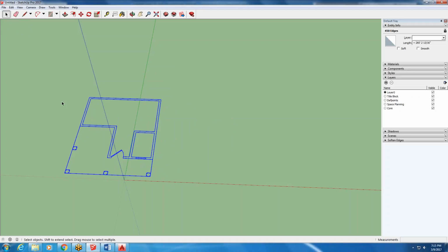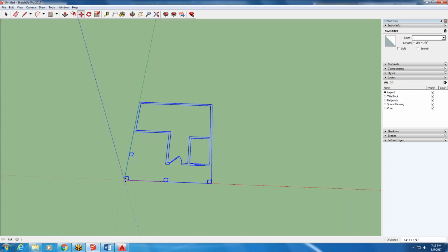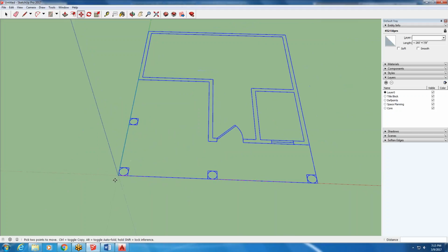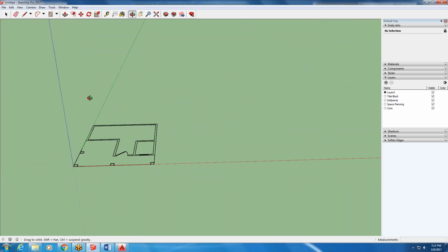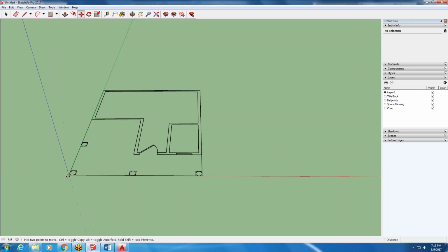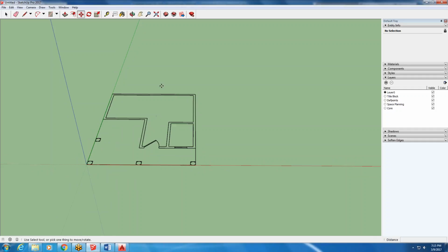Then I'm going to click. I always like click this arrow to get out of stuff when I'm not sure about it. Then I'm going to select it again and move it about this point to this origin point. It's snapped in successfully, and now I have it set up how I want it for homework with the pillar in the origin. That means that this wall up here is going to be our north wall.